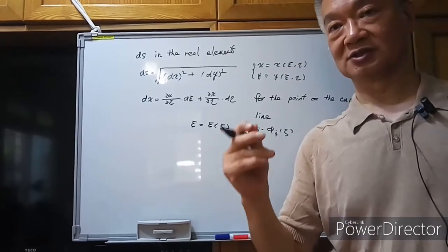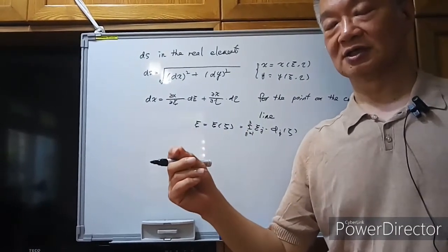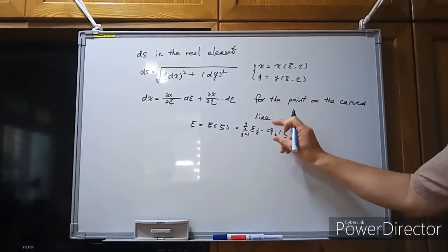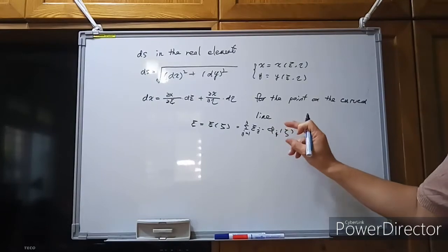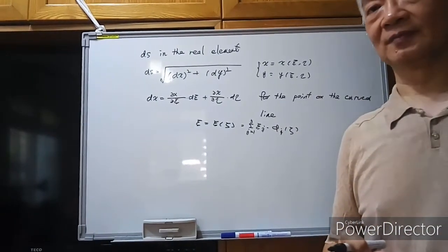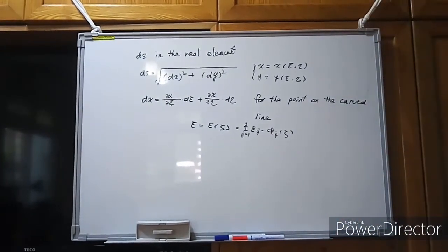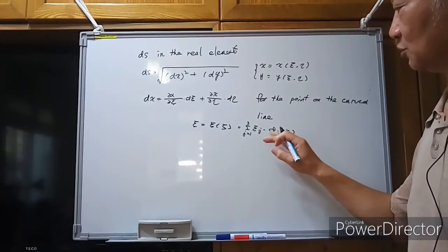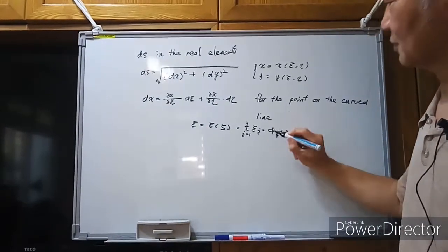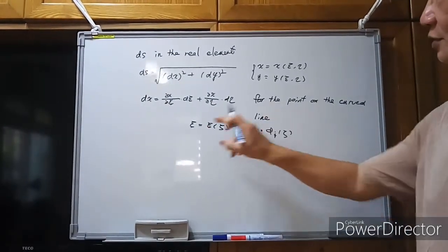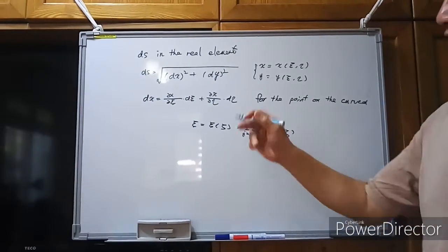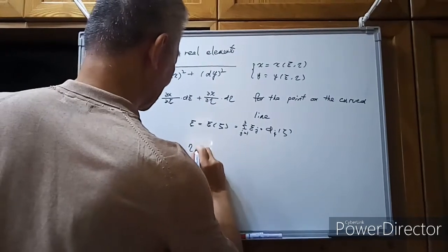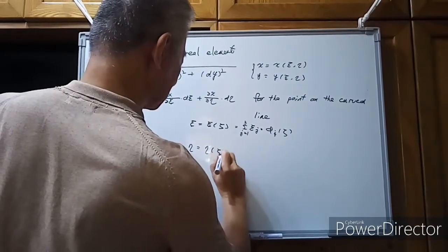We can use the three nodal points zeta equal to -1, zeta equals 0, zeta equal to +1, to establish the corresponding Lagrange interpolation functions. The interpolation functions are multiplied with the nodal values, and you need to sum them to get the c on the curved line. Also, you can calculate the eta. Right now, the eta is also a function of zeta.